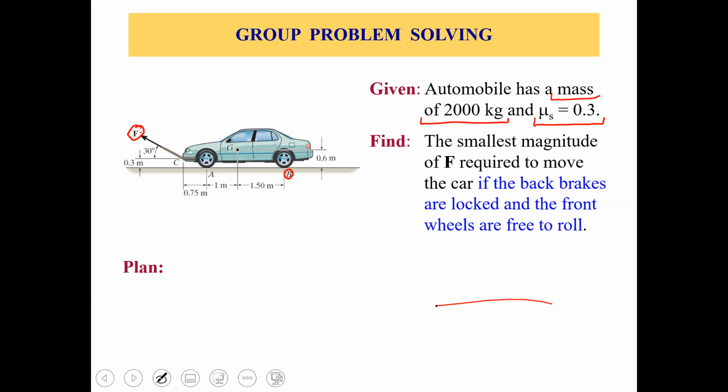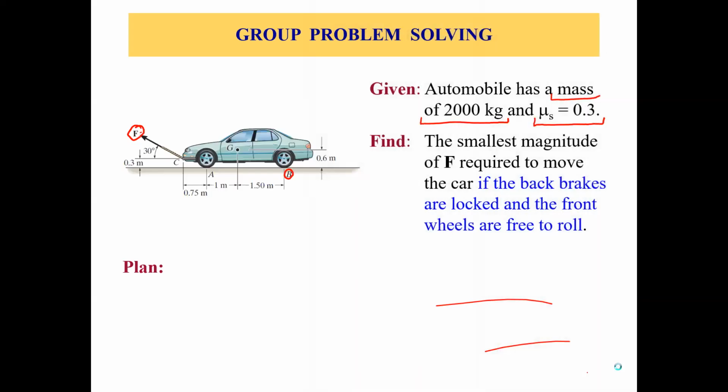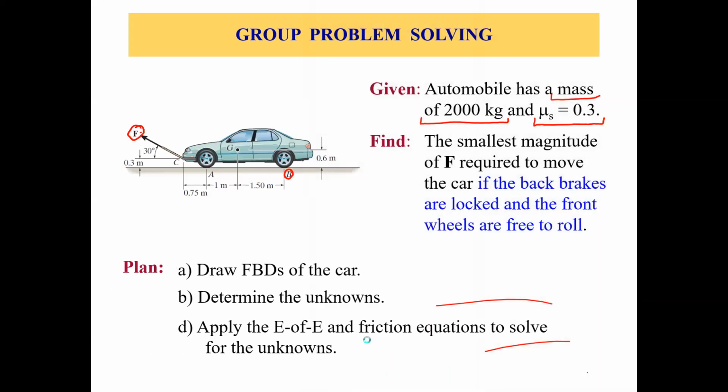Now, what are we going to do? Let's see the steps. Draw the free body diagram of the car. Then determine the unknowns. How many unknowns do we have? Then apply the equations of equilibrium and friction equations to solve for the unknowns.